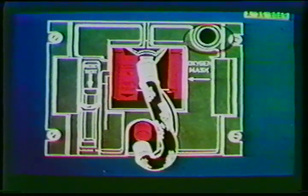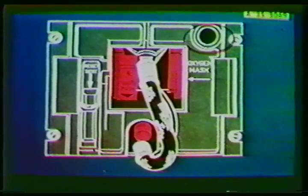A test, reset, slide control is used to test the mask in the stowed position. On the front of the oxygen mask compartment is an indicator that shows oxygen flow. No flow when black, and supplying oxygen when a cross is showing.